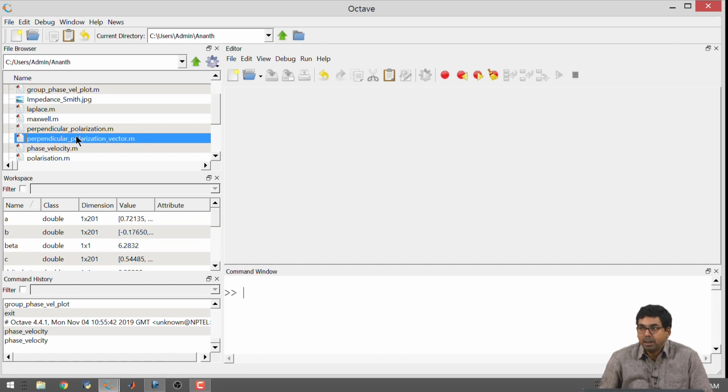For the rectangular waveguide, you may need to write some 3-dimensional Maxwell equation code that will have Ex, Ey, Ez, Hx, Hy, Hz, and you will have a solution in all the 3D space and 1D time. Then you have to take a slice and solve. It's too hectic. So, in this case, we are reducing the problem from 3 dimensions to 2 dimensions. First of all, parallel plate waveguide, you can just draw it as one conductor on the top, one conductor in the bottom, filled with some material inside. So, it can be represented in the cross sectional form.